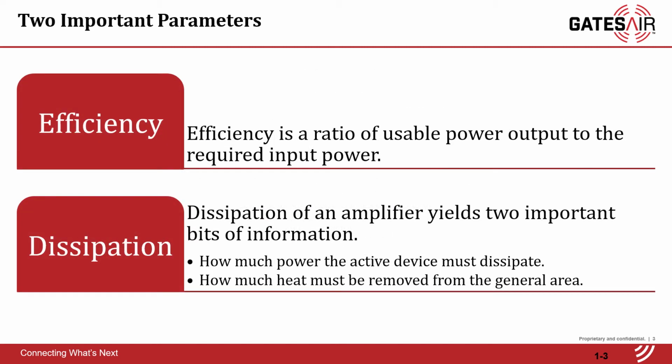As we saw in Pod 1, the source power will equal the desired power output plus the undesired inefficiencies of the transmitter system. These inefficiencies are in the form of heat. The thing to remember is that if you feel heat, that is waste, and you paid for that heat at the power meter. Plus you pay to remove the heat from the equipment and the building. Air conditioners have to be oversized when you are dumping a lot of heat into the room.